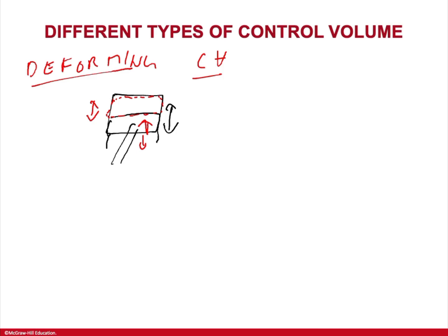So in this case, if we go back to the question, is the control volume deforming? The answer to this would be yes.